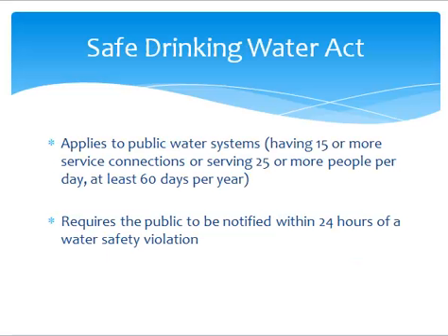In regards to water quality, in 1974 Congress passed the Safe Drinking Water Act, also known as SDWA. While this is a very extensive act, 2 points are important to note. First, the SDWA applies to public water systems, or those that serve 15 connections or 25 people per day for at least 60 days a year. Secondly, the SDWA requires that the public be notified within 24 hours of a violation.